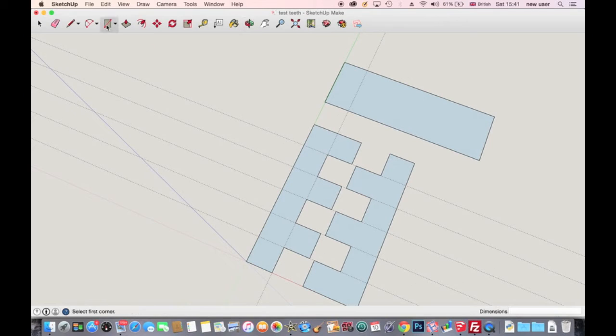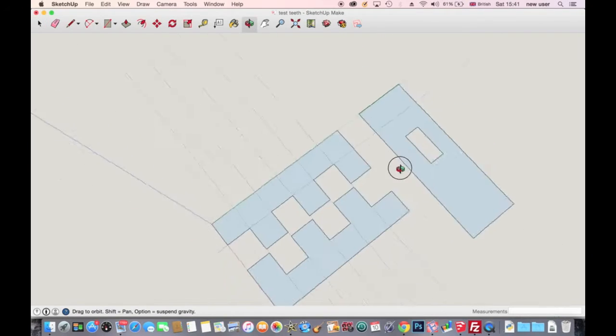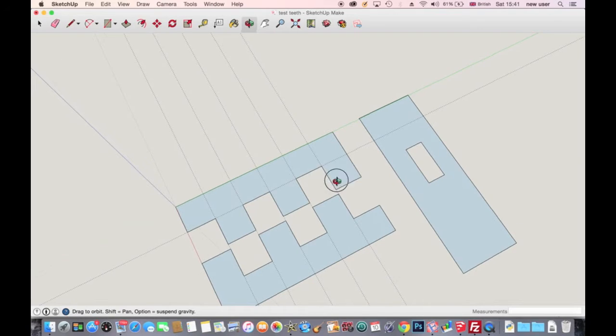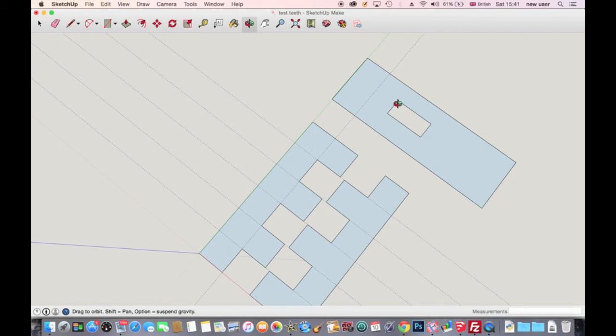It will export faces, and what it also does, which I've found lacking in other G-code exporters that I've used which aren't actually integrated in SketchUp, because it has the awareness of where the face is, it will offset to the outside of this face, but then on a hole in the face it will offset to the inside of the hole. So all your dimensions should be precisely how they are when you put them into SketchUp.